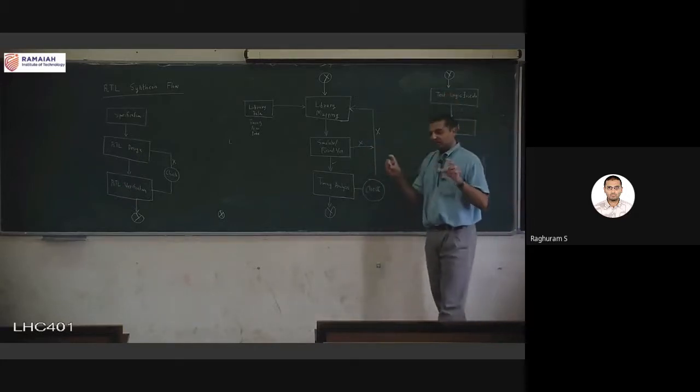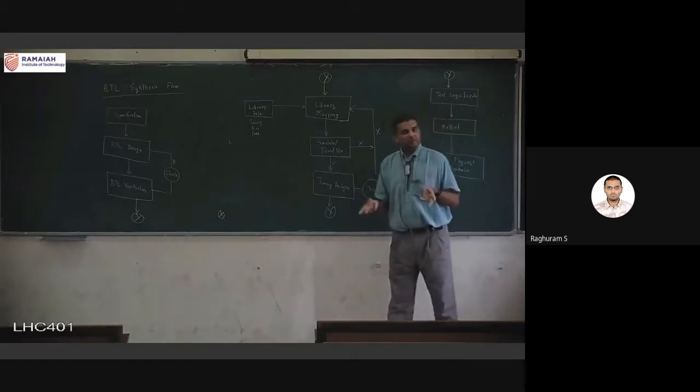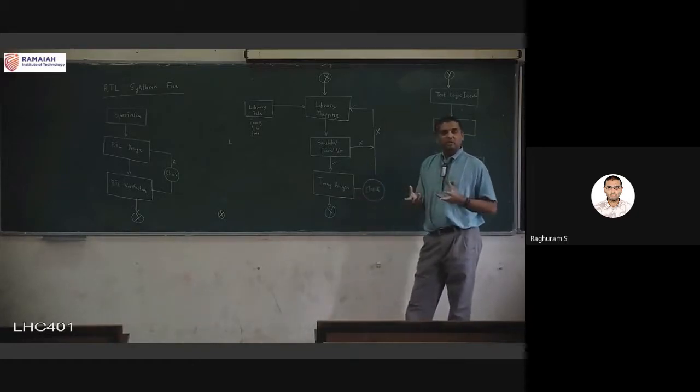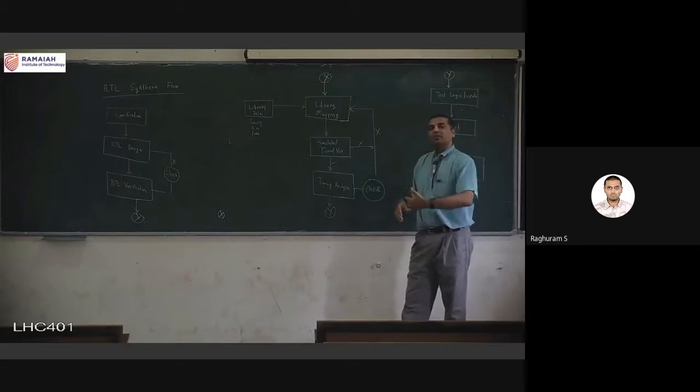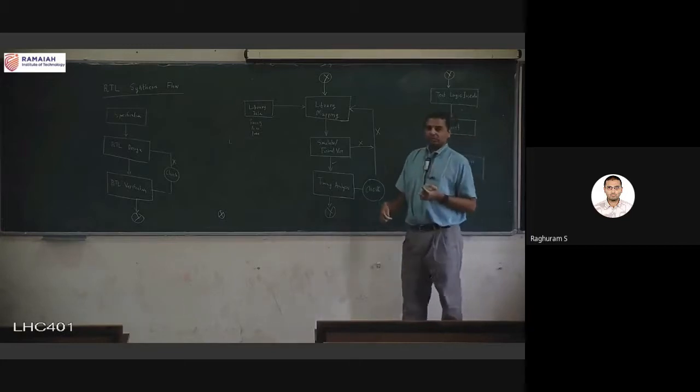So these are all special registers, for example. They could be special logic also sometimes. But generally, these are a different set of inputs which are easily accessible. Okay, these are not the primary inputs. These are easily accessible, and through these, I will feed whatever pattern I want. Okay, I cannot do that otherwise.